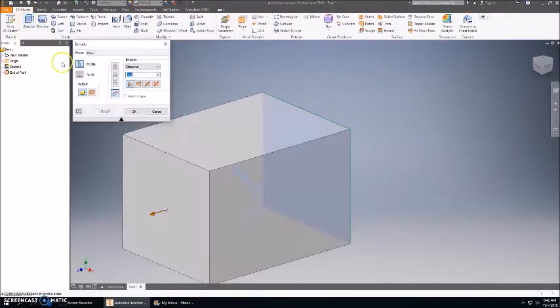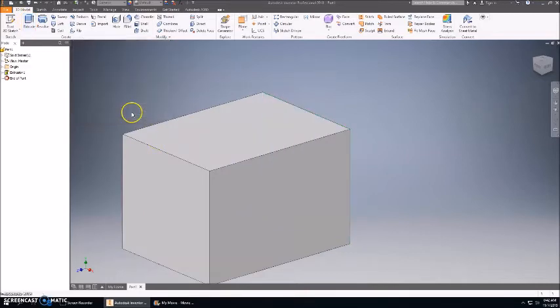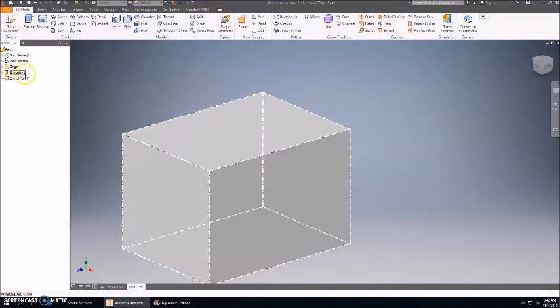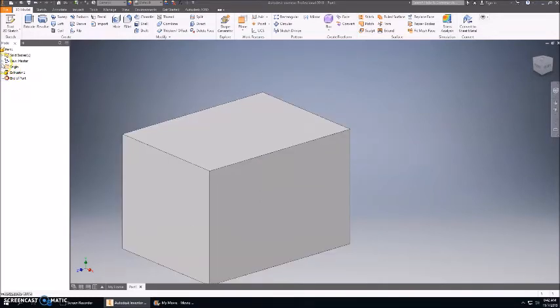Now I'm going to add a feature to that sketch, okay? And we're just going to extrude that. And now you can see that that sketch turned into Extrusion 1. Over here, these little carrots are called the parents and the children. I know it's a weird term, but it's what they use. You'll hear it referenced in a lot of Inventor videos.